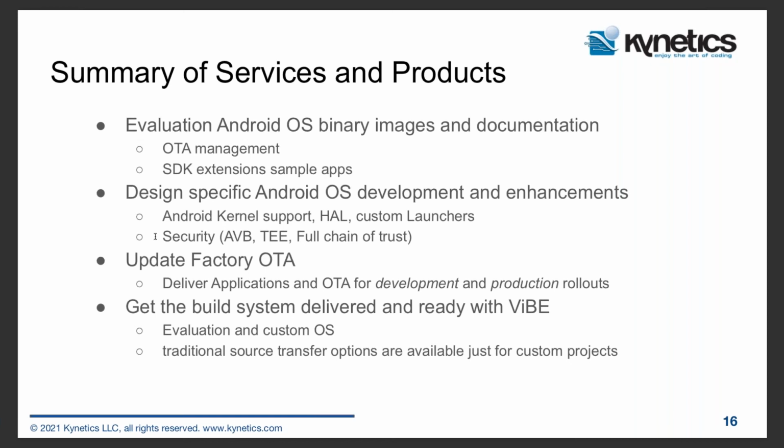We provide all the security for production systems, so support for Android Verified Boot and the Trusted Execution Environment. We already have Android 10 running on the Nitrogen 8M Mini featuring, for a customer, the Trusted Execution Environment. And of course, the full chain of trust, where we are also signing the bootloader for the complete chain of trust.